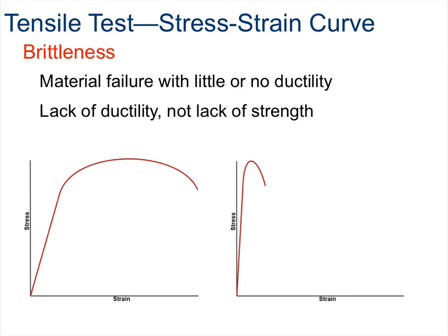Various stress points along the engineering stress-strain curve are often referred to with the term strength, such as yield strength and ultimate strength. However, this practice is not technically correct because the concept of strength is directly related to force, not stress. It's more appropriate to refer to points on the force displacement diagram using the term strength and points on an engineering stress-strain diagram with the term stress.